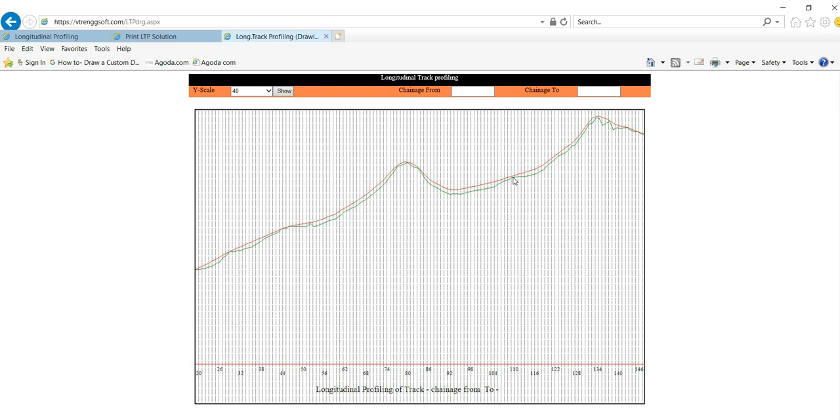Suppose we are lifting, what will happen? That platform height will be reduced and may lead to some infringement. That is why some obligatory points would be there, and those points should be taken care of. And there, if you want to restrict the lift at a particular station number, you can give your option. That is, you put zero.